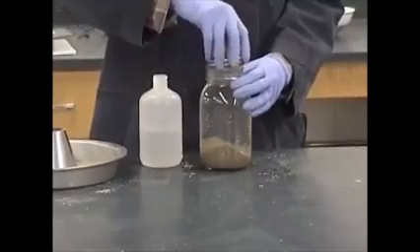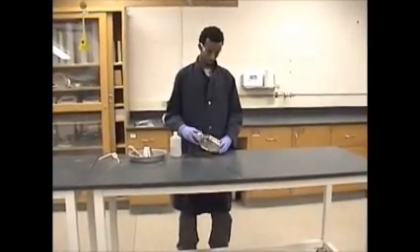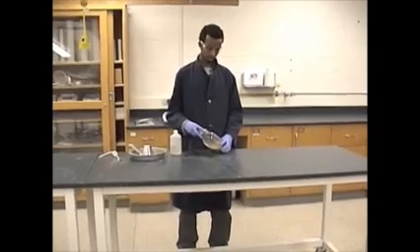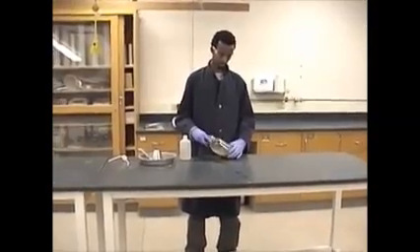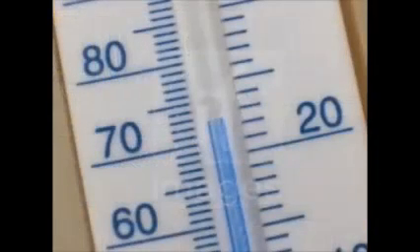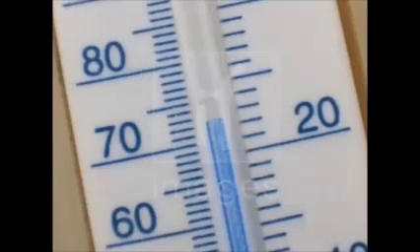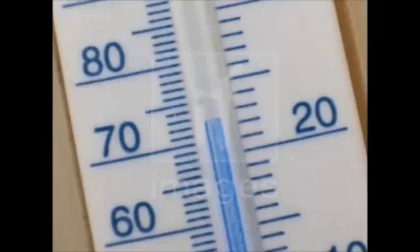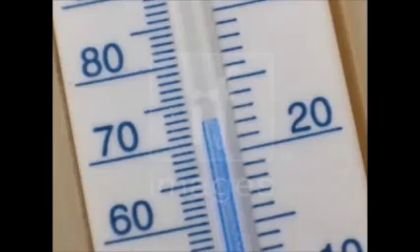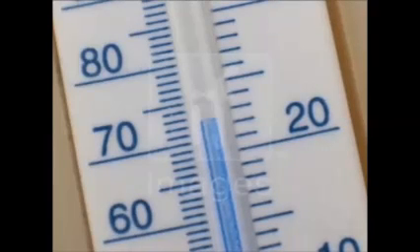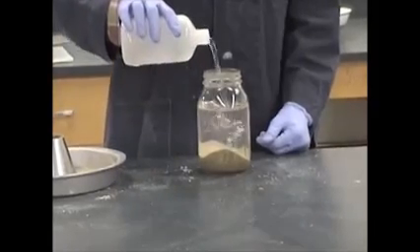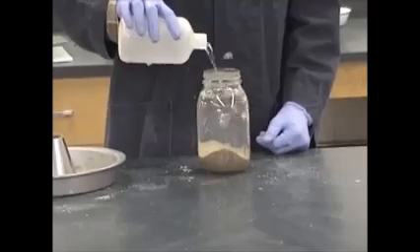Now that all of our materials are back in the mason jar, we want to roll, invert, and/or agitate our mason jar. We can also use mechanical methods to ensure that we remove all of the air bubbles. Once all the air bubbles have been removed, we want to adjust the water temperature, if necessary, to 23 plus or minus 1.7 degrees Celsius. Remember, for ASTM this is 23 plus or minus 2 degrees Celsius, by immersion in a circulating water bath. Once this is complete, we can bring the water level back to the calibrated mark.